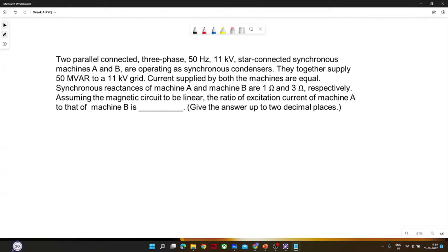One question was asked in the batch: if a synchronous machine is running as a reluctance motor, then what will be its speed? Synchronous reluctance motor is another type of synchronous machine itself. The difference between a conventional synchronous machine and this reluctance motor is that it works on the principle of reluctance, and its speed would be synchronous speed only. So, nothing else than synchronous speed.